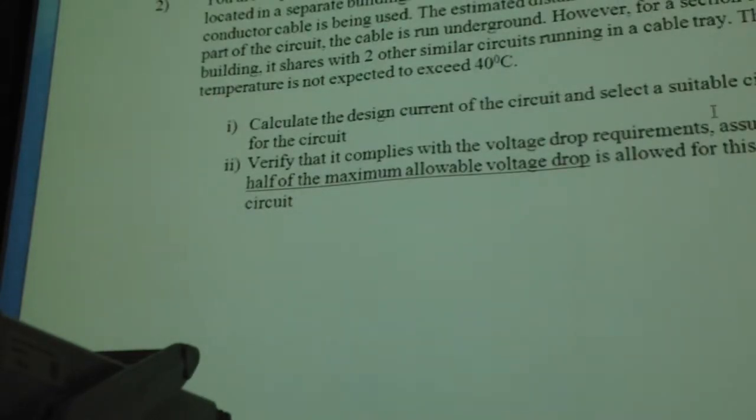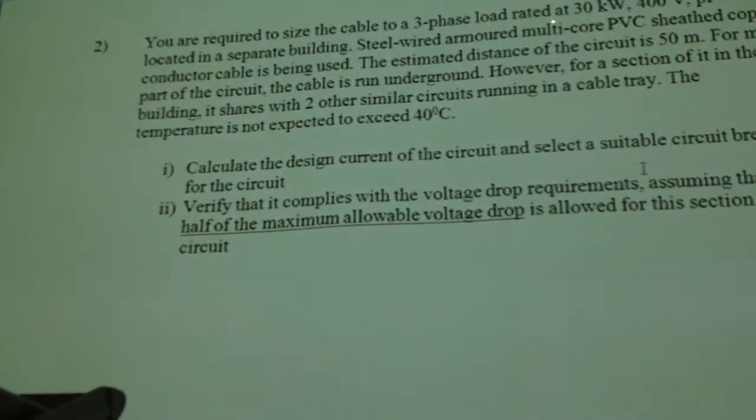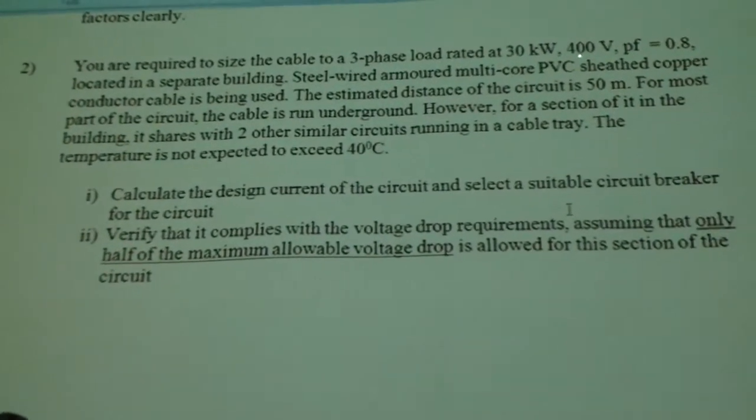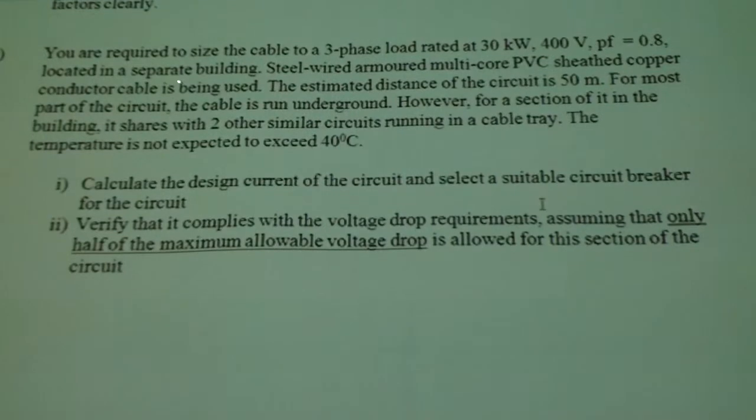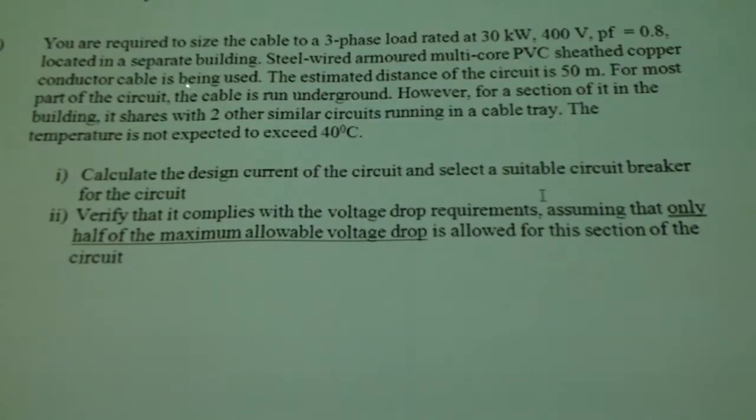The second question: I need to size the cable, select the cable size. It is a three-phase load, 30 kilowatt, 400 volt, power factor 0.8, located in a separate building. Steel wire armor, multi-core PVC sheath, copper conductor is being used.